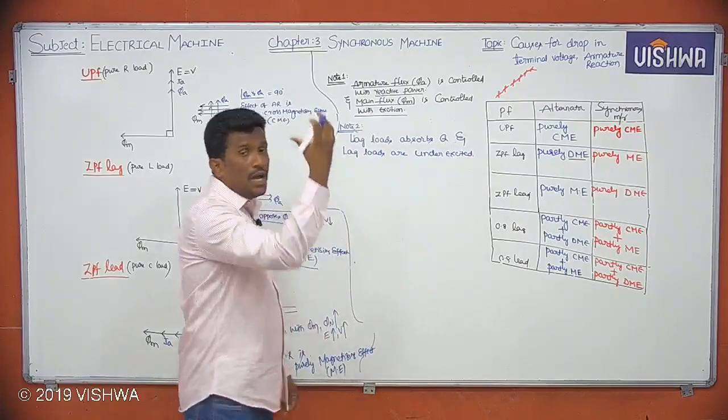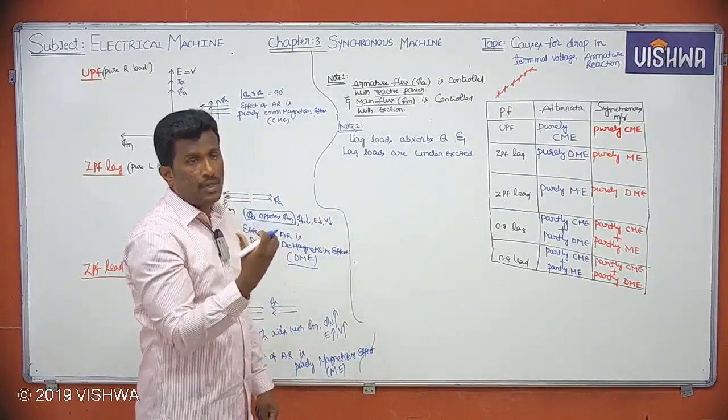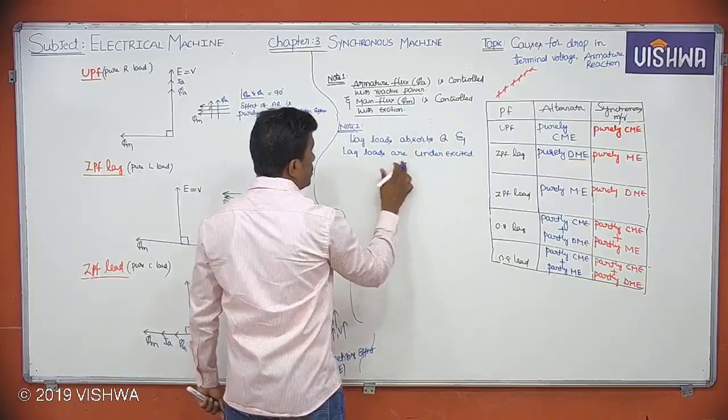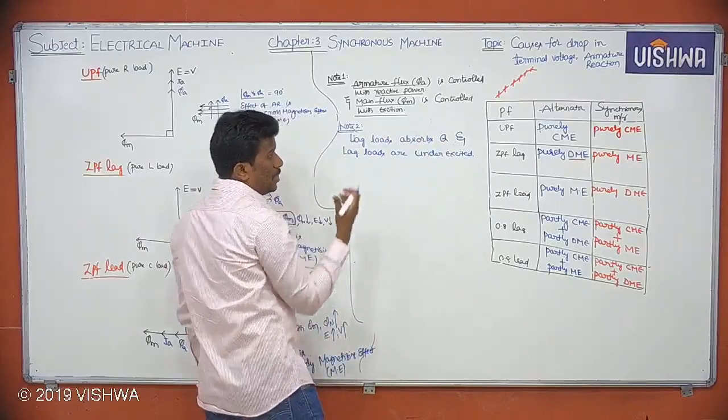They absorb reactive power, right? They are taking reactive power. Therefore, lag loads absorb reactive power, and lag loads are under excited.